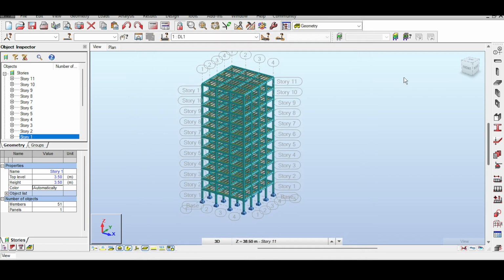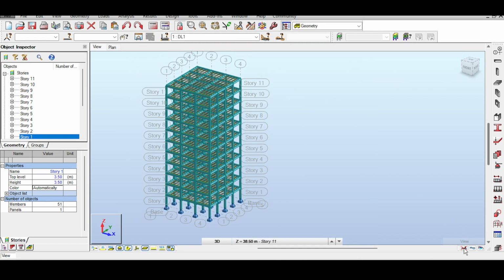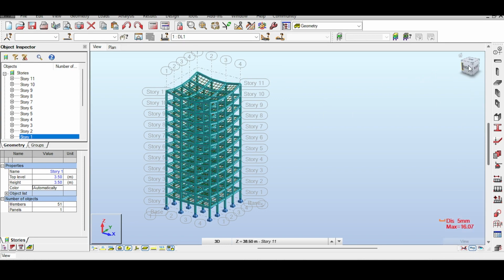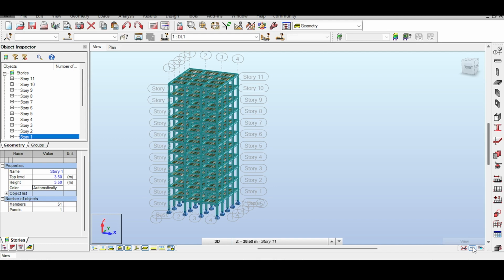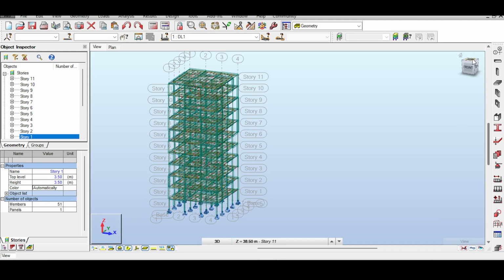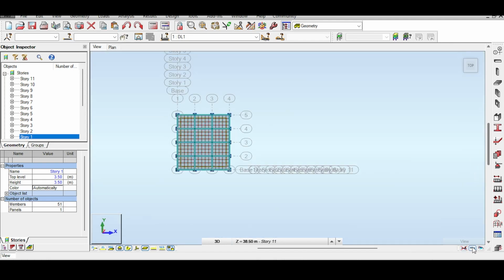It's not going to take long. So, okay, it's got analyzed, and I click on the displacements deformation, and you can see the structure deforming vertically. Like if I open the deformation and close, you can see the structure deforming vertically. There is no sideways motion. How do I know that? If I go to top and enable the deflection, nothing changes.